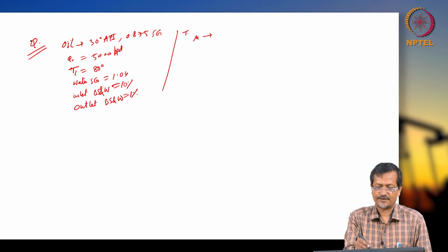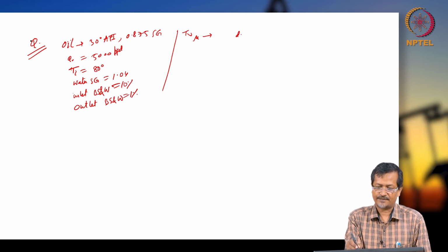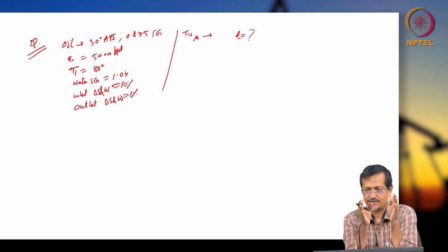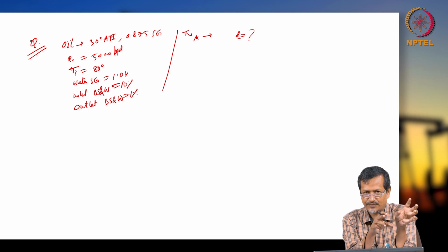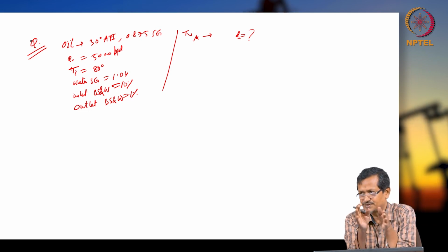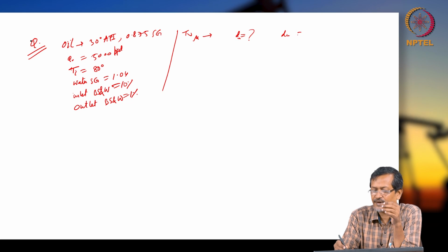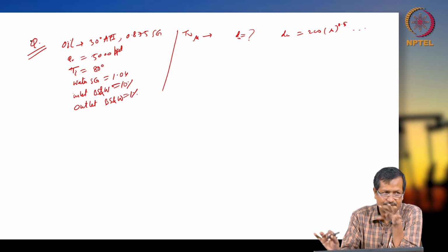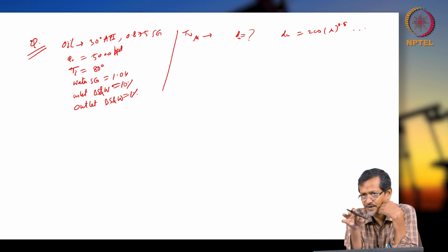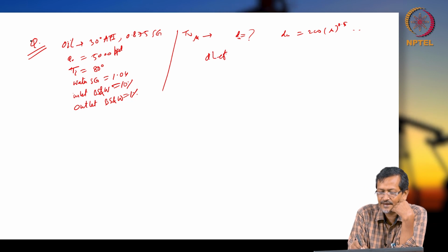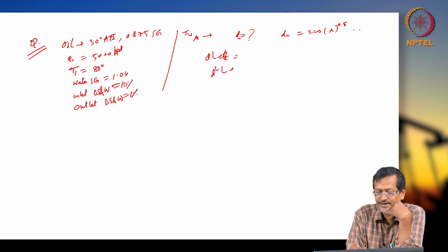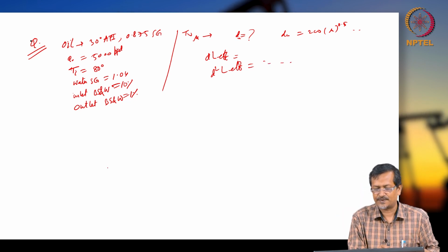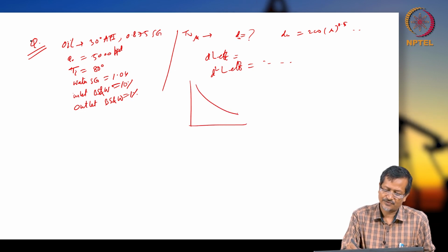after that only you can calculate d, particle size is not given, dm. Okay. Then the steps are that first you get viscosity data, from formula you can collect or use chart. Once you got viscosity, then dm formula you apply, 200 mu per 0.25 within that range. Once you get dm, then you can get d LEFF, okay, d square LEFF, this parameter you can get. Once you get this parameter, then you draw the curve.